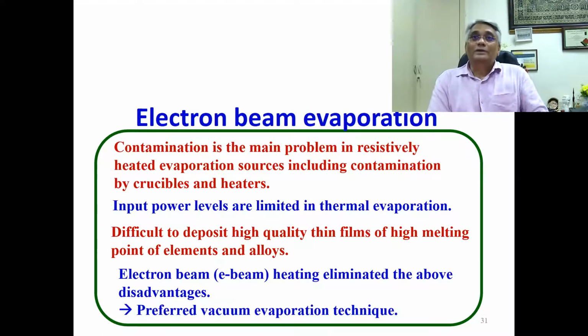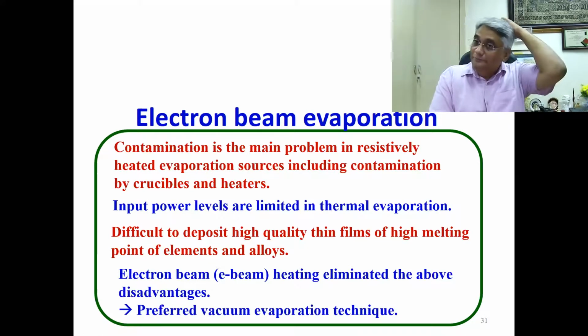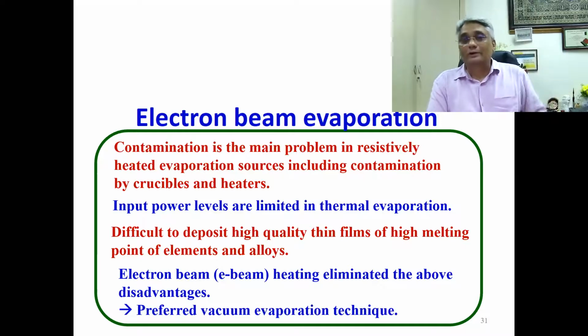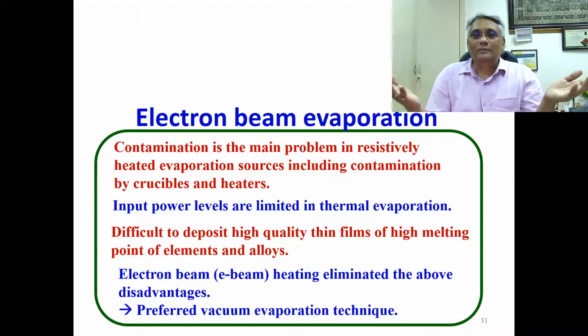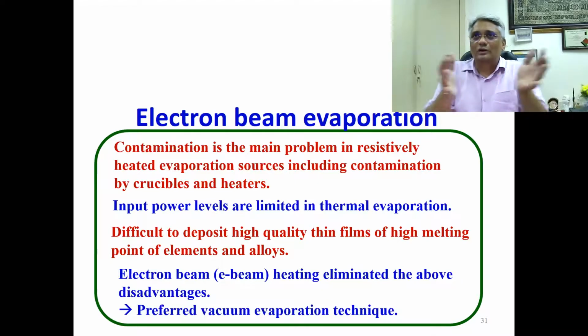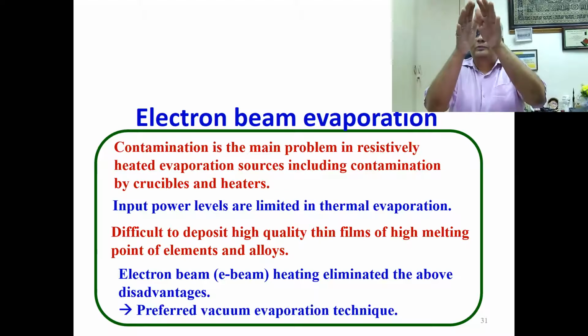You see, if you go by the theory of the thin film growth process, in order to get directional evaporation, so I'm evaporating from here, I want the emanated species to move towards the substrate in a highly directional way. But in thermal evaporation, it's not happening. It's non directional because there is not enough energy for these species to move in the upwardly directed way.